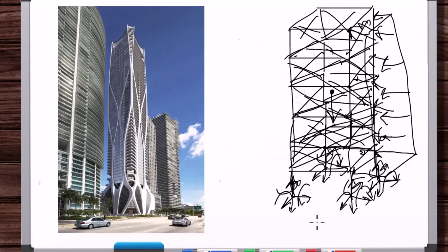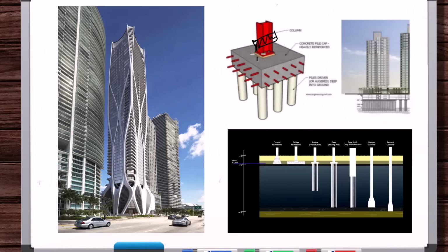Right? Because these bolt forces can't resist moments. They can only resist translation. But the net effect of all this: there are 4 bolt forces here, then 4 bolt forces at the other beam, so there are 16 total bolt forces. As a group, they resist the moment. They don't allow the building to tilt. But the way you represent the forces, you don't put moments there.